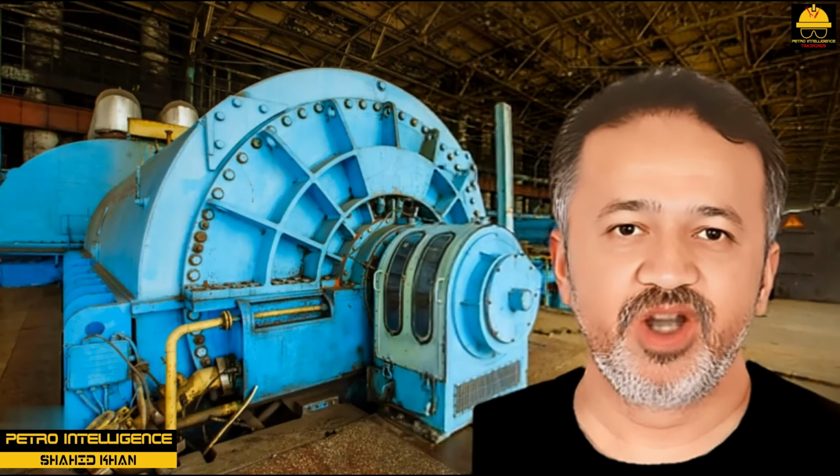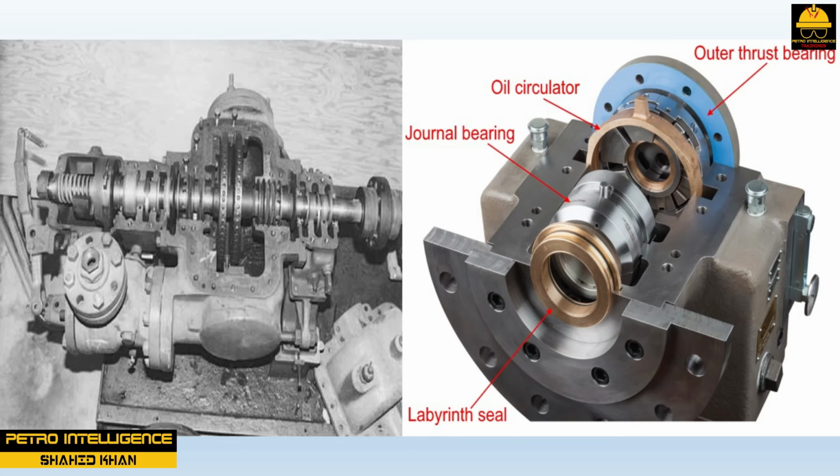Seals. Carbon ring and labyrinth shaft seals are located at the end of each casing along the rotor. These devices are used to minimize the outward leakage of steam under pressure and the inward leakage of air. Carbon rings prevent leakage between the rotor shaft and the casing. The stainless steel spring-backed ring gland is mounted in a corrosion-resistant sleeve that is kept from rotating by a rod passing through the lower housing section. Labyrinth seals consist of a series of ridges and intricate paths designed to stop flow.